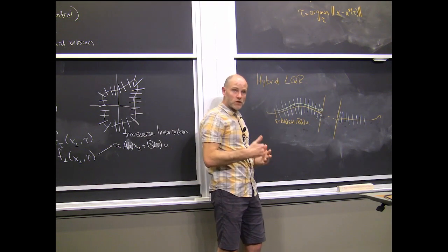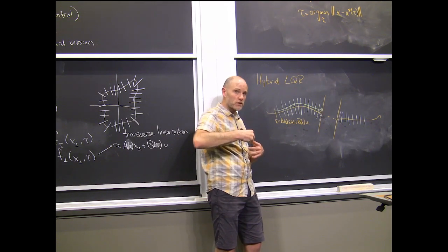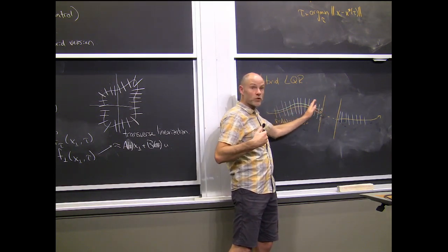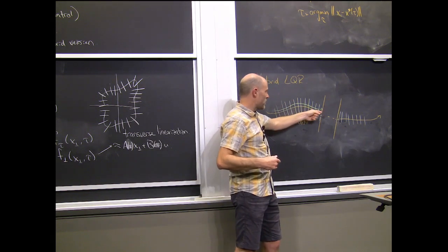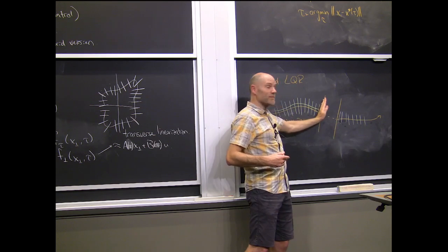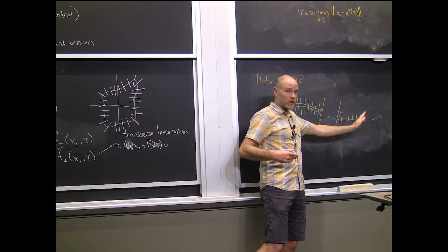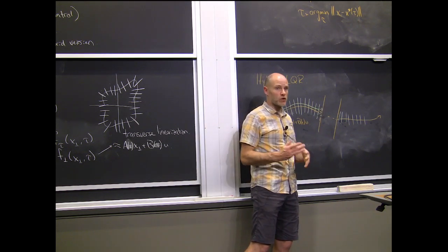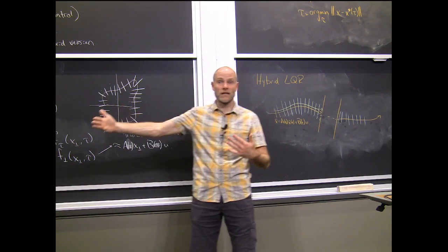The transverse coordinates, where tau is projected to the closest point on your trajectory, is safe under projection along the orbit. So it's okay to slow it down or speed it up. And so in the case where the perturbed system had a premature impact, it's okay to keep using the gains here until the nominal trajectory gets over there, right? Same thing for a delayed impact. It gives you the recipe for continuing to use the correct gains and not just evolving blindly in time.